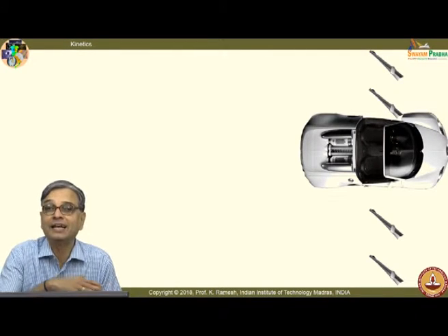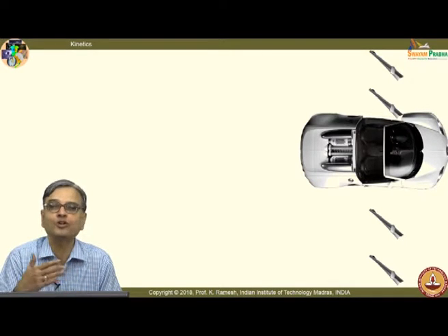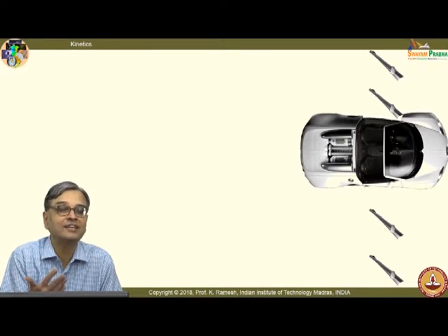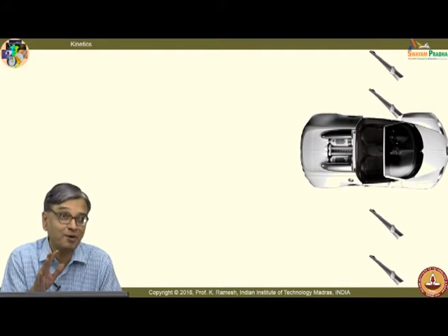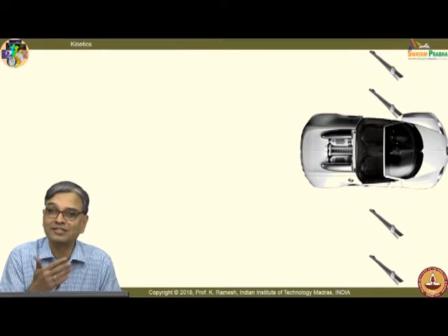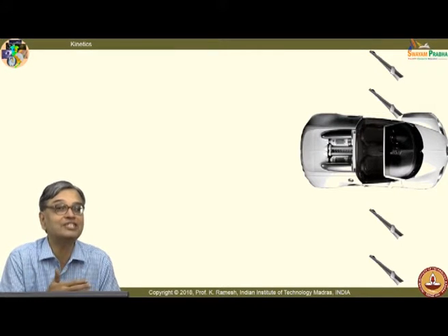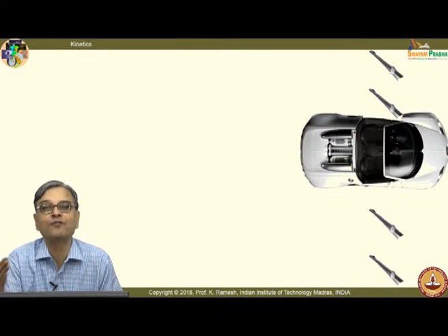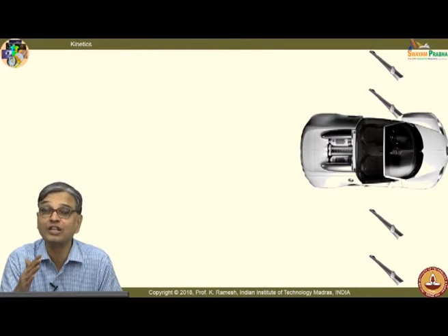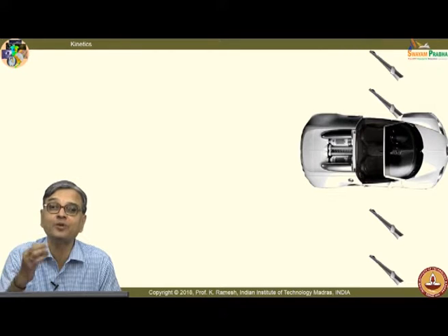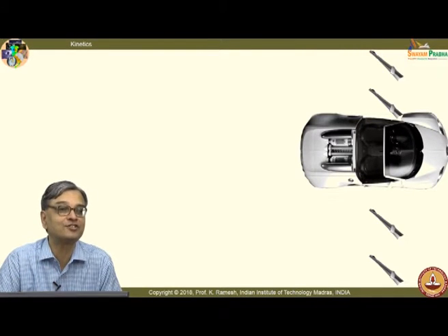So, you have a reasonable appreciation of what is happening to the door, and you should also recognize, to start with, how the door was. What was its angular velocity? All that is hidden in the problem. Fine. That is what you have to look at. That is why I have put this animation. You have a very important clue. It starts from rest, so omega is 0. It starts from 0 angular velocity and acquires a finite value of omega when it reaches 45 degrees. You should recognize all that. Only when you recognize all that, will you be able to use the appropriate equations to handle it.